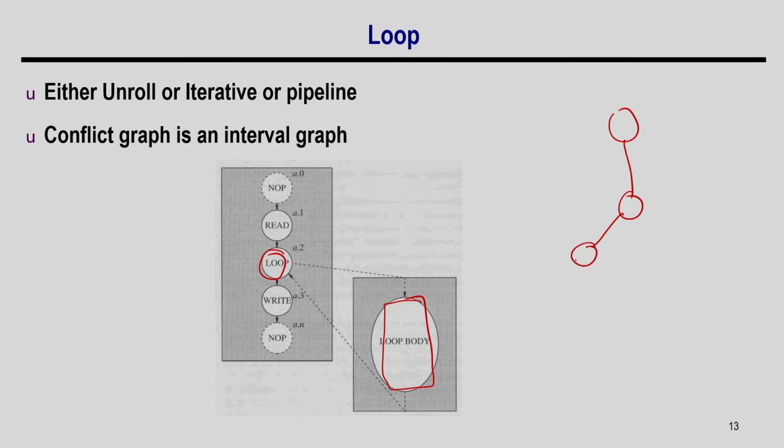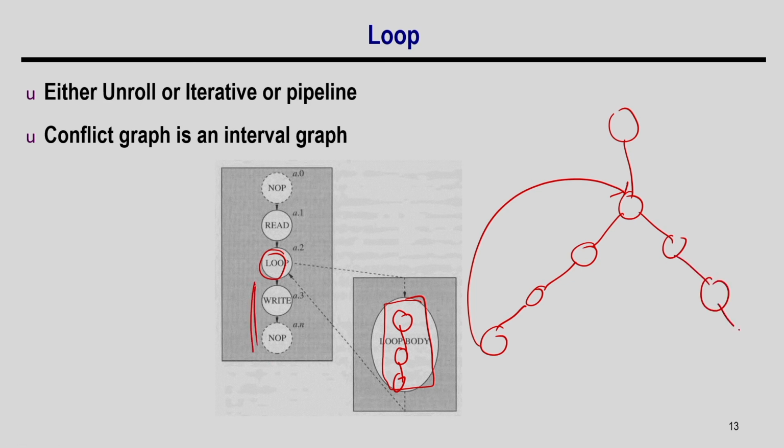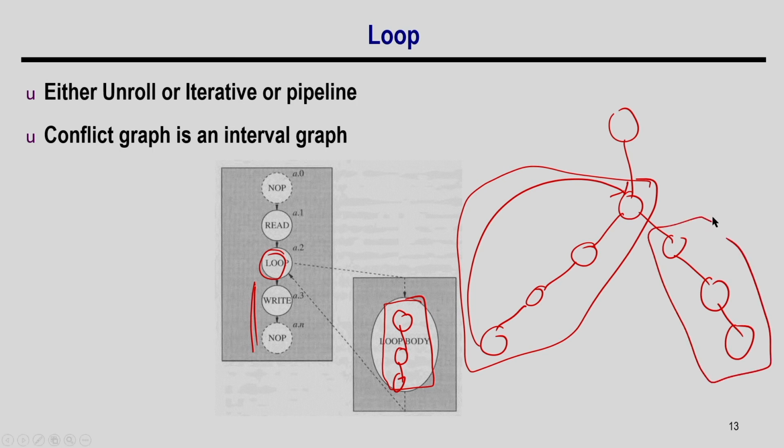Say this loop is executed in 3 cycles. So, this loop body has, say, 3 cycle operations, and this is getting repeated. Now you see here in the combined graph, whenever I am going to execute the whole thing in hardware, whatever operations follow the loop have to wait till this loop is done. This loop has to execute separately and then everything has to wait, and similarly